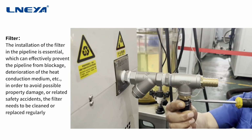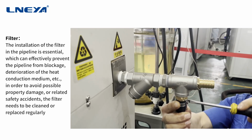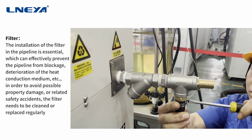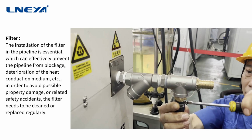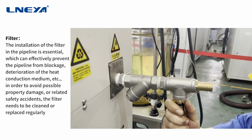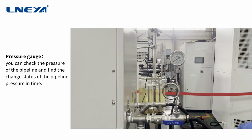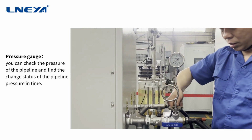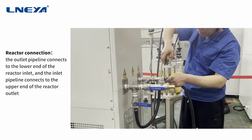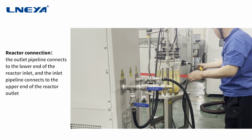3. Filter. The installation of the filter in the pipeline is essential, which can effectively prevent the pipeline from blockage, deterioration of the heat conduction medium, etc., in order to avoid possible property damage, or related safety accidents. The filter needs to be cleaned or replaced regularly. 4. Pressure gauge. You can check the pressure of the pipeline and find the change status of the pipeline pressure in time. Reactor connection: the outlet pipeline connects to the lower end of the reactor inlet, and the inlet pipeline connects to the upper end of the reactor outlet.